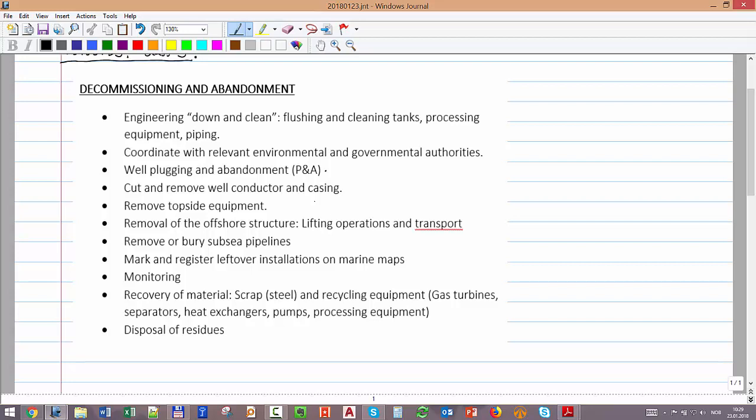Maybe you're going to cover it in some other course, but basically I have to remove the Christmas tree and the tubing that is inside the well, and I have to put in a cement plug, at least 2 of them. And it's almost like drilling. You have to move a drilling rig, do a cement operation, and retrieve the tubing. So I need a drilling rig for this process. It's extremely expensive, but it has to be done.